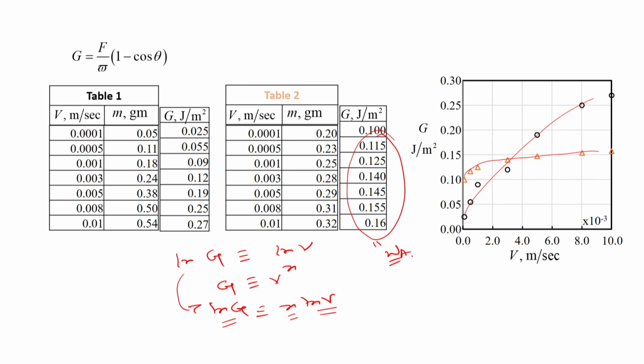Now, why this happens can be because of various reasons. One is that the adhesive itself may be elastic, not viscoelastic. Another is that the surface at which this is attached, the adherent substrate, is a non-dissipative interface, in the sense that the rate dependency is very low.